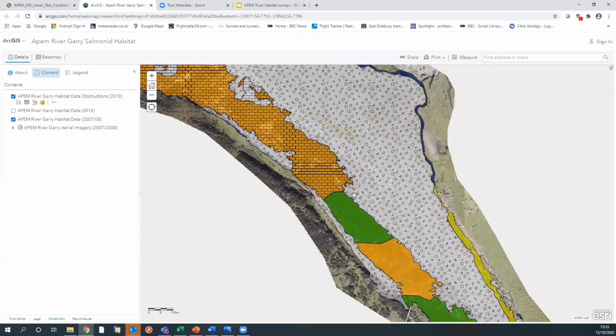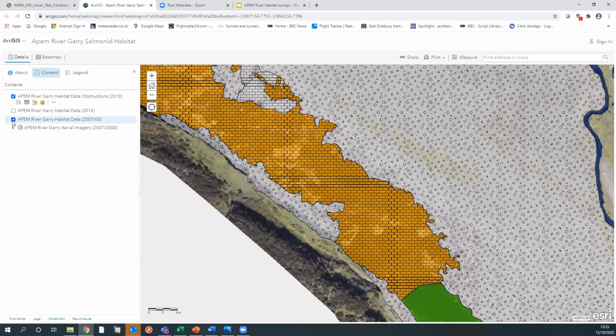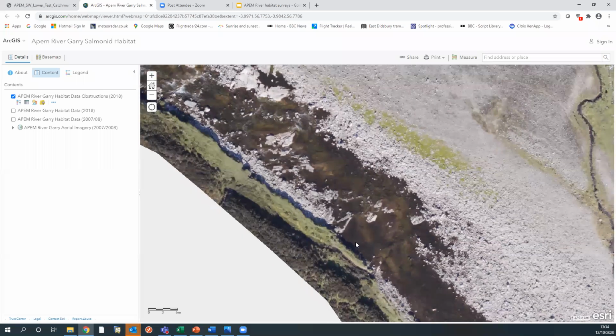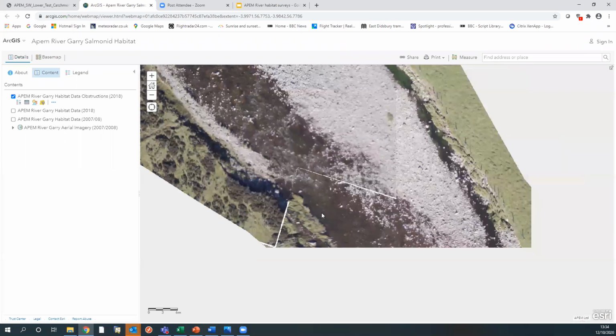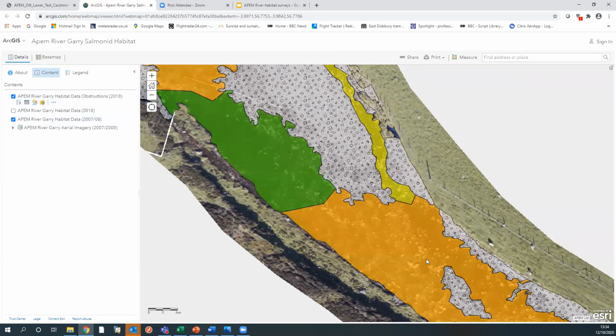So, for example, here they've mapped that this was bedrock habitat. Essentially, as hopefully you can see from the imagery, there's no gravel or anything at the bottom. That's just straight to bedrock. So from a fish habitat point of view, passageway but not particularly usable. And then further down here, where we're getting the gravels and the different flow types, that's when we're getting the different kinds of juvenile parr and mixed juvenile habitats and fry habitat.